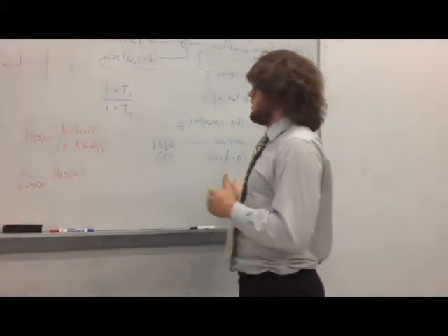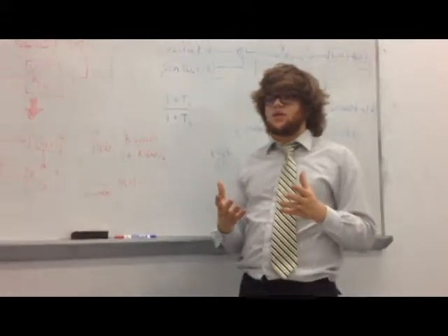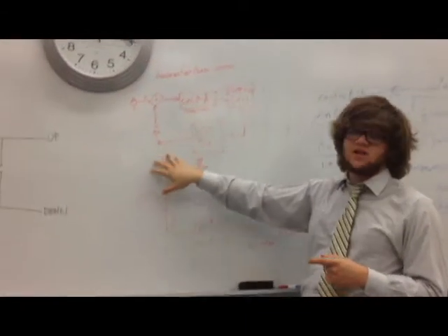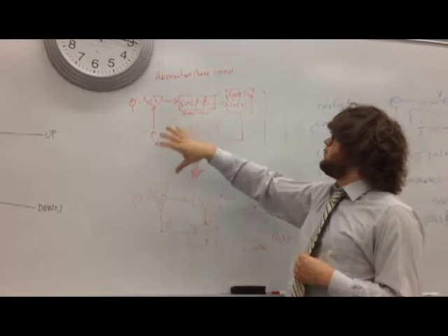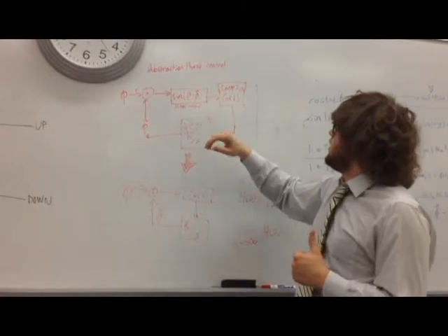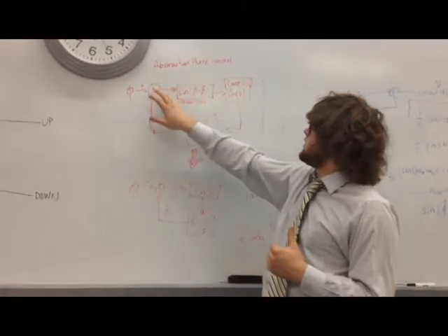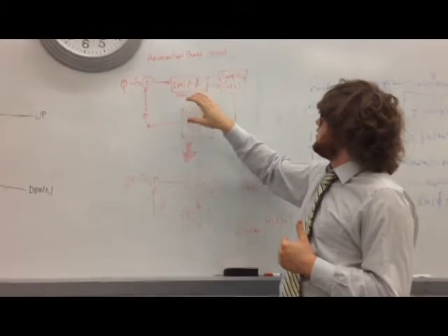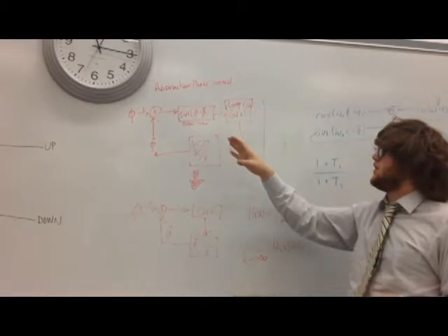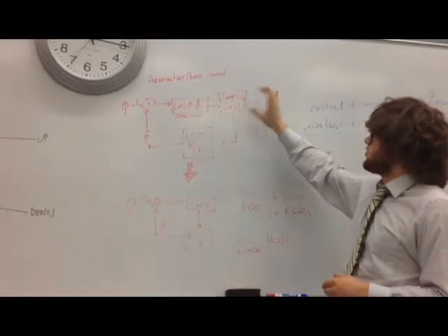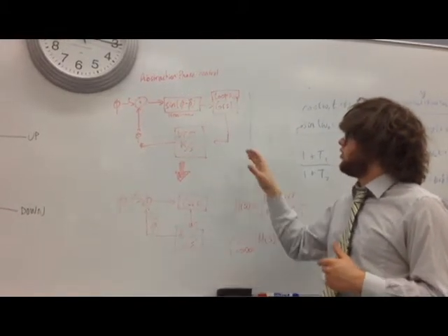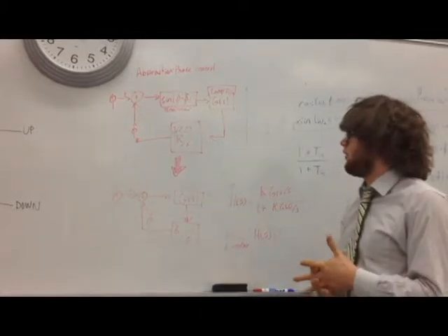Knowing this, we're going to stop thinking about this control system in terms of voltages and start thinking about it in terms of phase. This is an abstraction layer. Multiplying the voltages is the same as comparing the phases, so we'll compare the phases here. Then you have the sine of that phase difference, which is the nonlinear part of the system. We filter out any high frequency components, put it through the voltage controlled oscillator, and get a phase estimate back out.